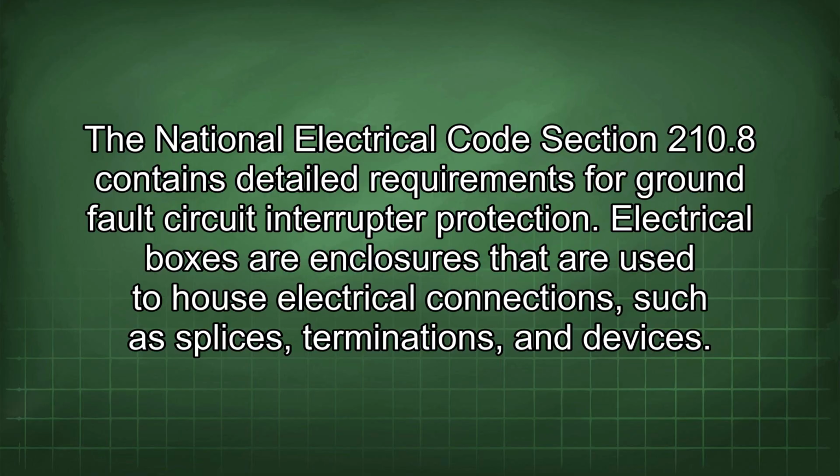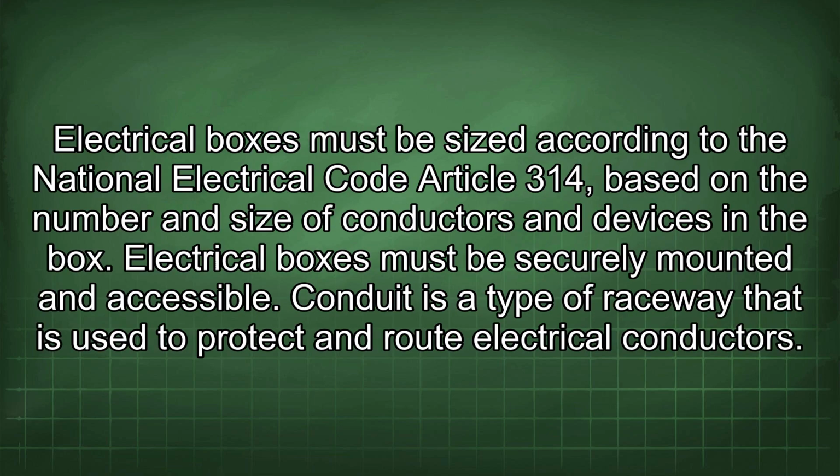Electrical boxes are enclosures that are used to house electrical connections such as splices, terminations, and devices. Electrical boxes must be sized according to the National Electrical Code Article 314 based on the number and size of conductors and devices in the box. Electrical boxes must be securely mounted and accessible.